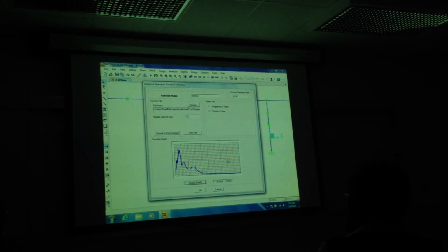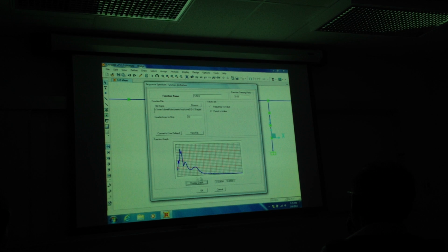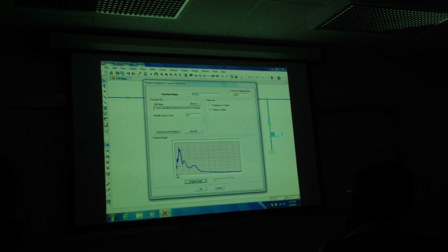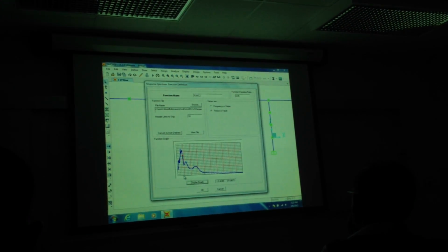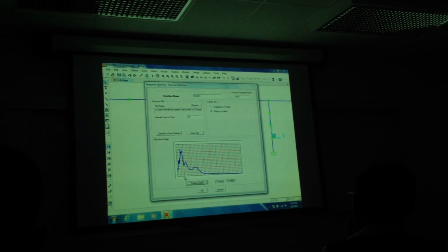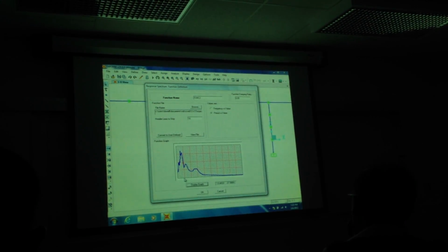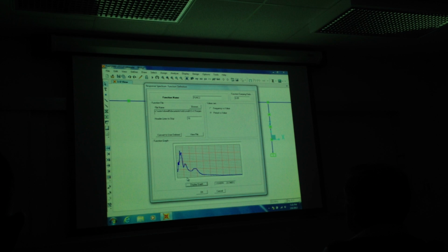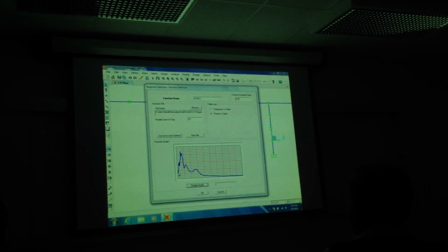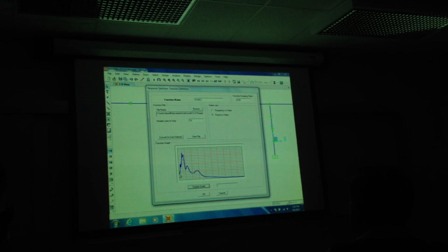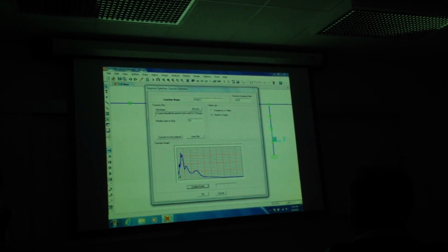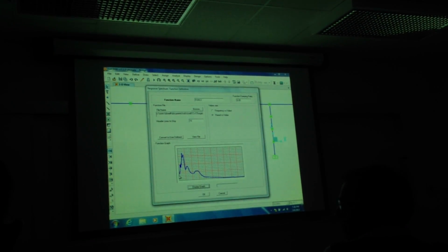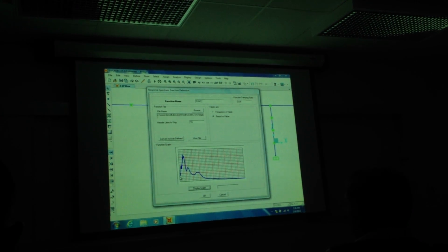And the way this is generated is, if you imagine this is the natural period this way, let's say a single degree of freedom oscillator, this is the acceleration on the vertical. And so if you have something that's a solid concrete slab bolted to the ground, it has essentially zero natural period, right? It's solid, it's rigid, it's just this thick, and so it's going to accelerate with the ground. And so the period is zero, so you move to the left, and then this would be the acceleration of that slab, and it's the same as the peak ground acceleration. And it's the maximum acceleration of the whole earthquake motion at that slab, which in that case is the same as it follows the accelerations of the ground.